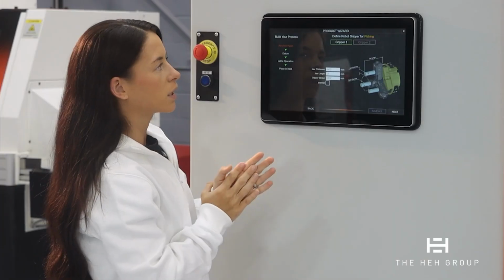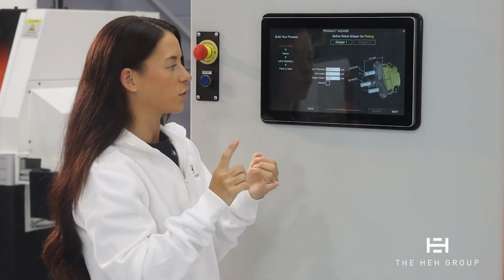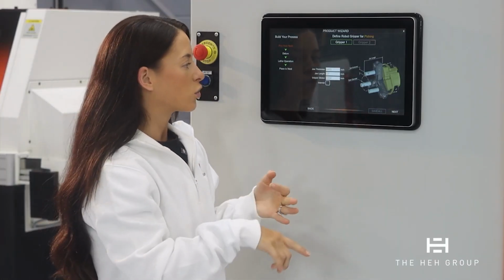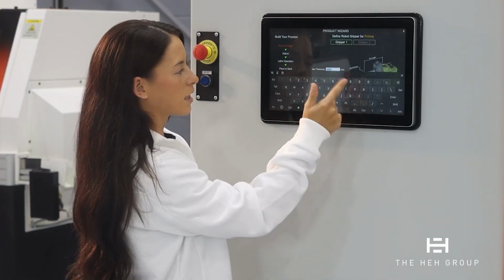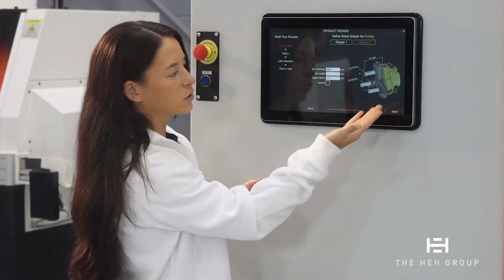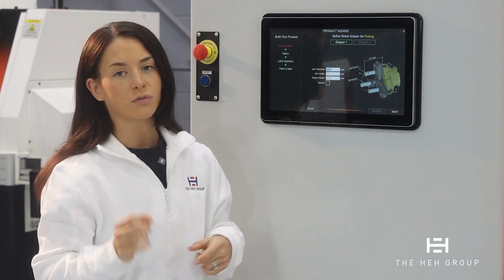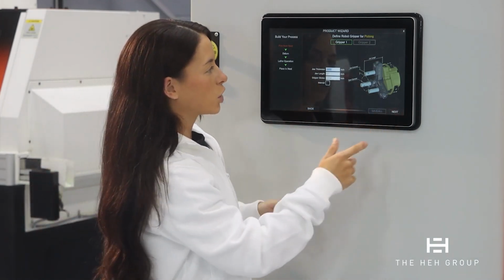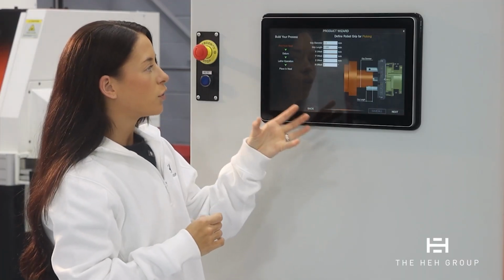This is really, really important. You want to make sure that you have accurate measurements of the gripper. It's going to ask you for the jaw thickness, jaw length, and gripper stroke, and these are super easy to edit. All you have to do is touch this and type in a new number if you need to. The nice thing too is Agile has these nice diagrams that tell you exactly what you're looking for and exactly where to measure. So if we keep moving forward here, now we're going to define the picking for the robot.